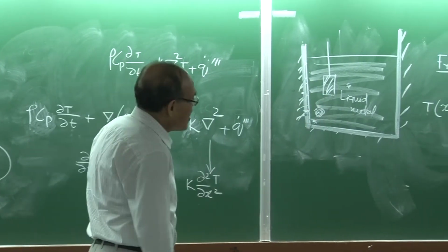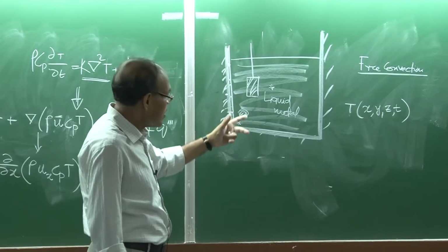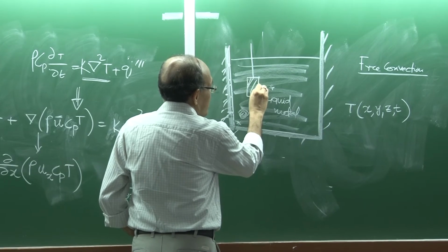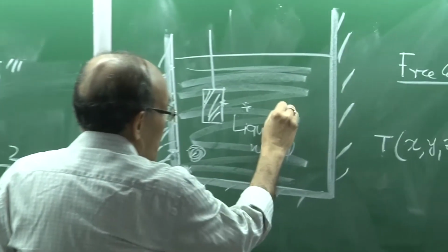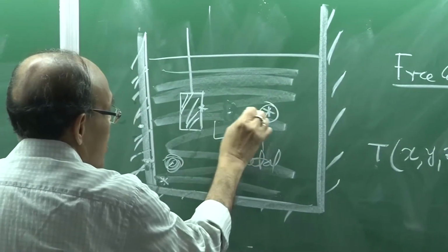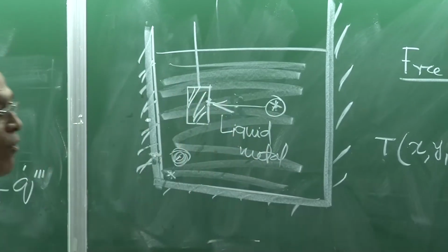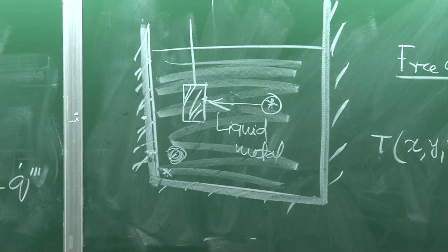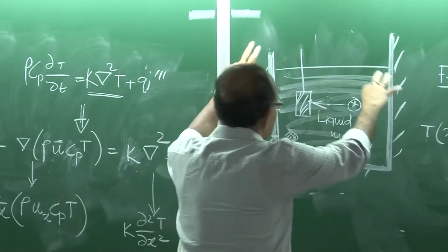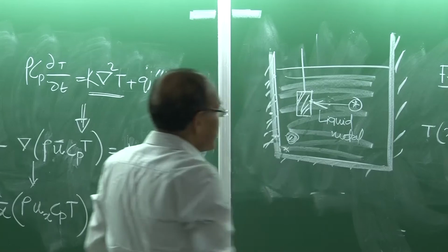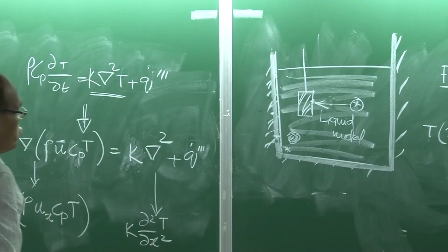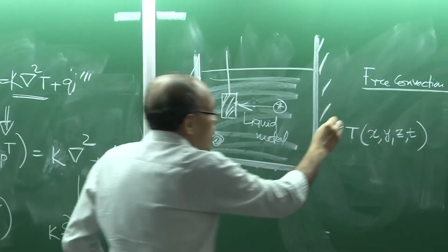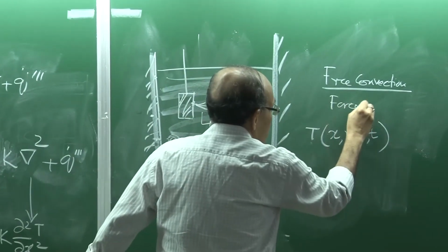And in certain cases, as you can understand, because there is a differential in temperature, the melting temperature here is 760 or 770 and the temperature here is 1600 degrees centigrade. So, there is a net flow of heat from the liquid to the solid surface. There is a class of problems where, even though there may be free convection currents in the system, there may also be some forced convection, as opposed to free, if you have some stirring.